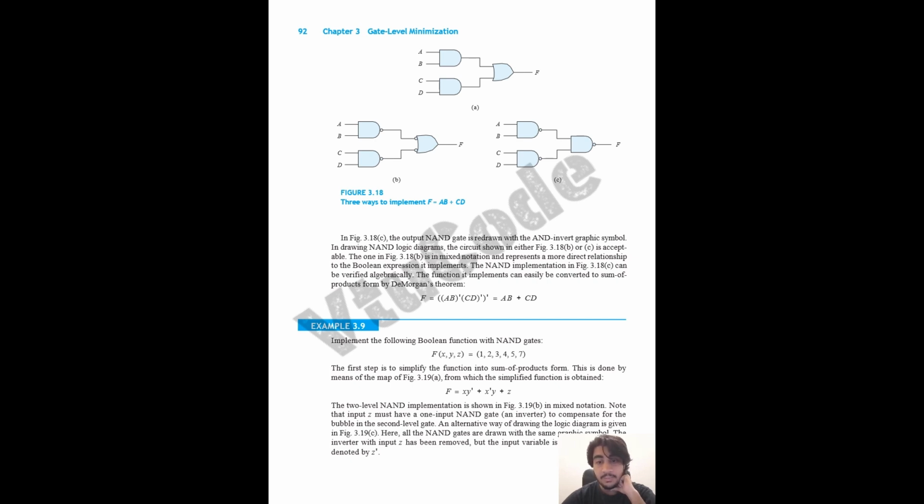So now how do we represent this using the logic circuits? That is very important. So here it's given x bar y plus z. So first we take x as an input line, y pass it to the NOT gate, get the output, connect these two to the AND gate.